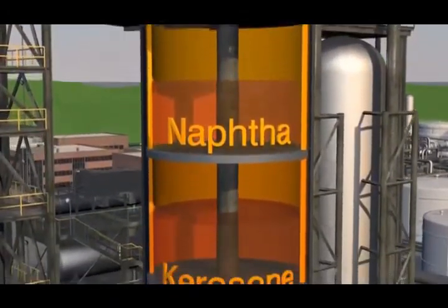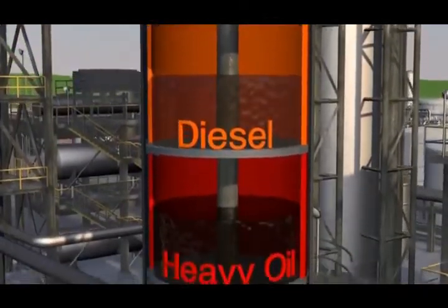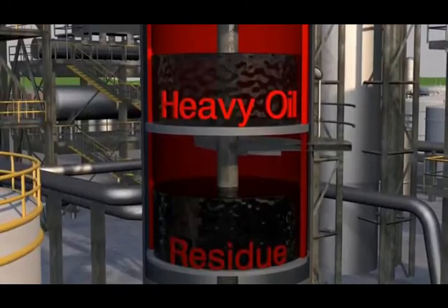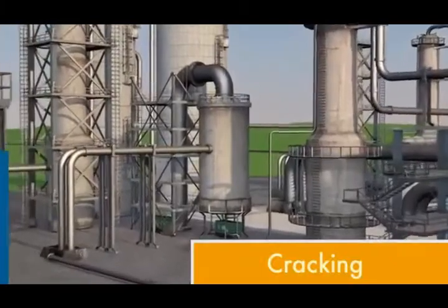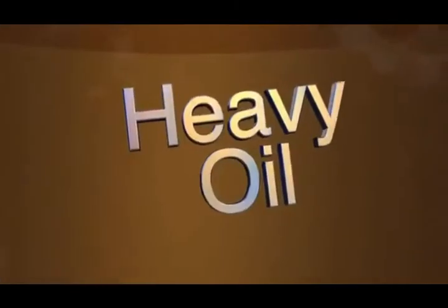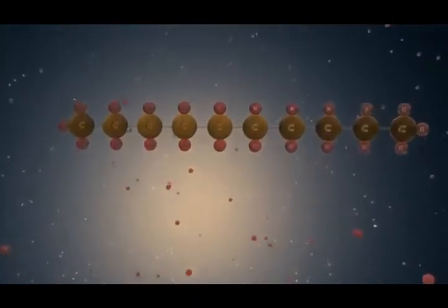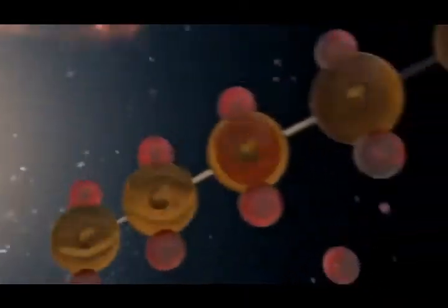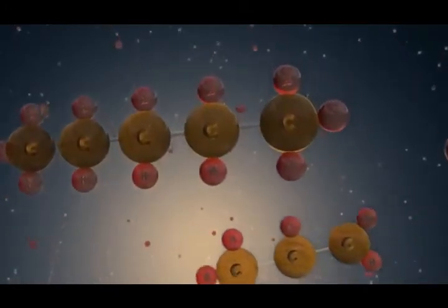The lighter and medium weight liquids require less processing before they're ready to be used in cars and trucks. The heavier liquids need more processing to become useful. A process called cracking is used to maximize the usefulness of heavy oil. Heavy oil has long strings of carbon and hydrogen molecules. Using a catalyst, these molecules can be broken into smaller chains, transforming the heavy oil into lighter, more valuable fluids.